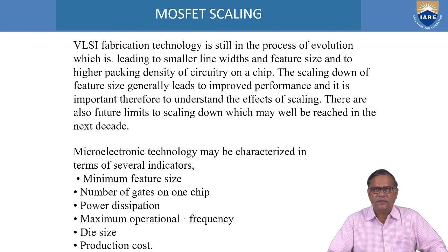VLSI fabrication technology is still in the process of evolution, and this is leading to smaller line widths and feature sizes, thereby causing higher packing densities in the chip. The scaling down of the feature size generally leads to enhanced performance, so it is necessary to understand the effects of scaling. Of course, there are future limits to scaling which may well be reached soon.